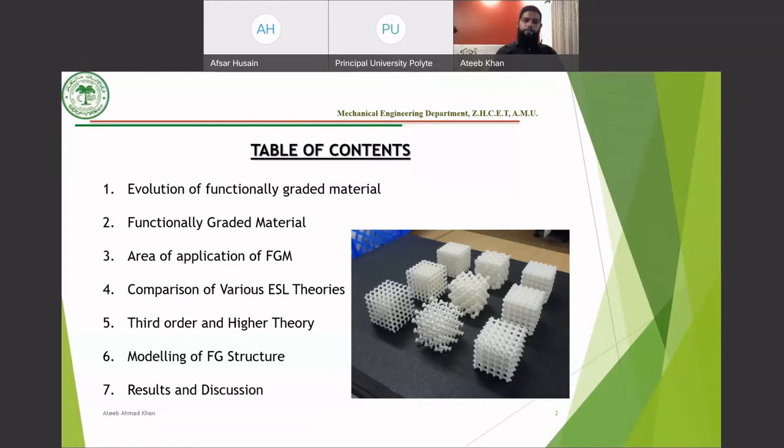The results extracted from Abaqus are for the cantilever beam, for the all sides simply supported plate, all sides clamped plate, and two sides clamped and two sides free plate. This is just for you to see the comparison between the simply supported conditions and the clamped conditions, and to verify that the results which I obtained from Abaqus are also in good agreement with the literature already present and with the in-house developed code.